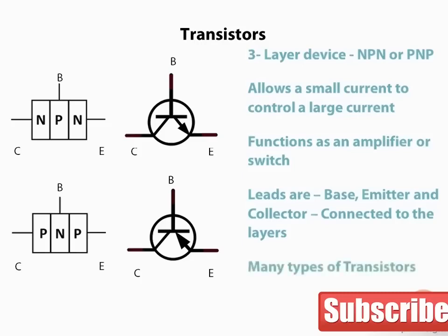There are many types of transistors. What is common to all transistors is that they all have 3 leads and perform the same function: controlling larger currents with smaller ones. The properties and application can be somewhat different between each type. Different types of transistors include field effect transistors, or FETs, metal oxide semiconductor FETs, or MOSFETs for short, JFETs, and unijunction transistors, to name a few. We're going to focus our study on the very humble bipolar transistor.